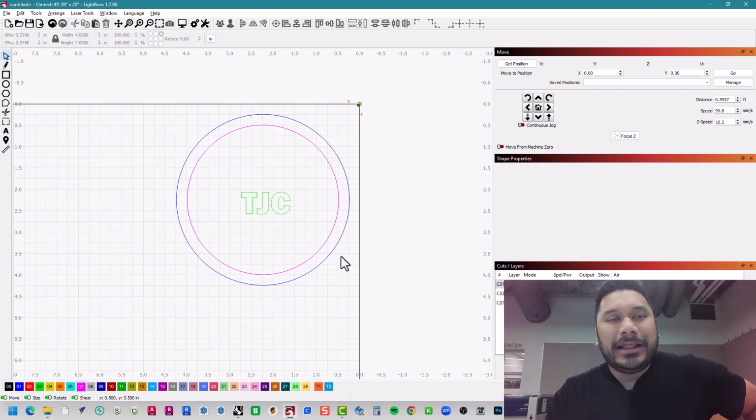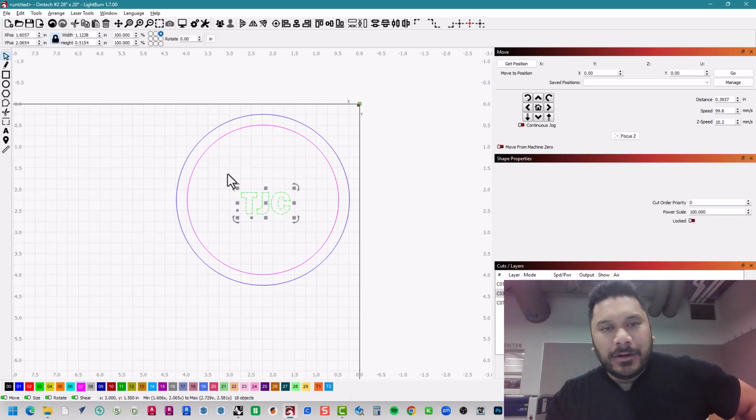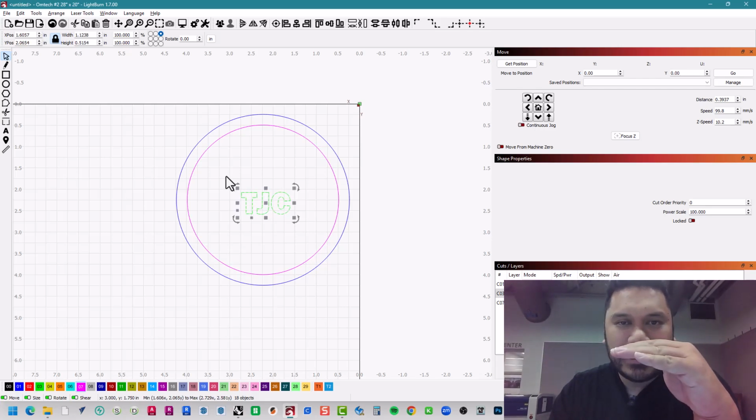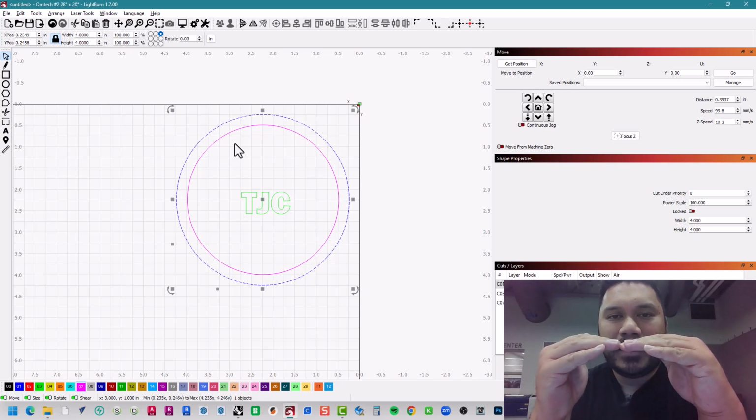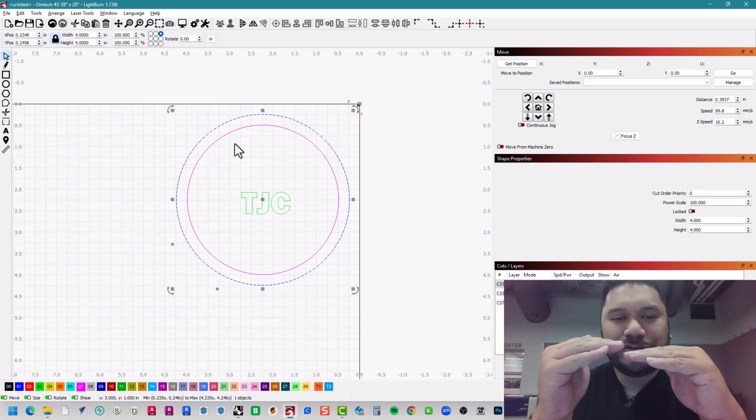And when you cut it out, because of the hex bed, because of the material, once you do that final cut, the coaster will actually drop down below even the bottom of the original material. So if we were to cut this out first, have it drop, then you wouldn't have that 19 millimeter height requirement between the engraving that needs to occur and the top of the surface. That won't be 19 millimeters anymore because it's dropped.